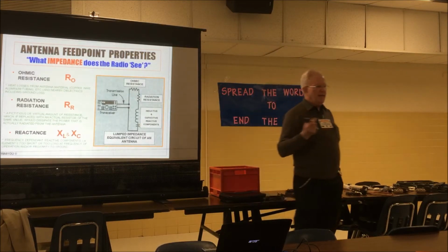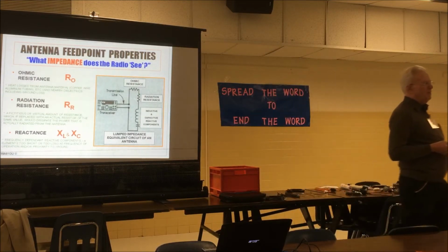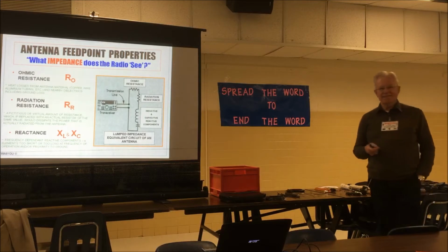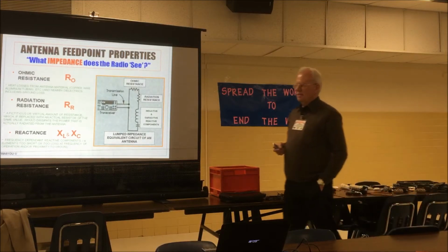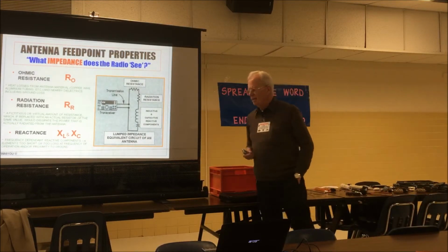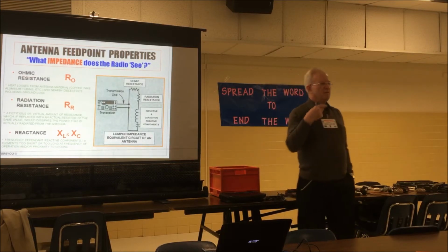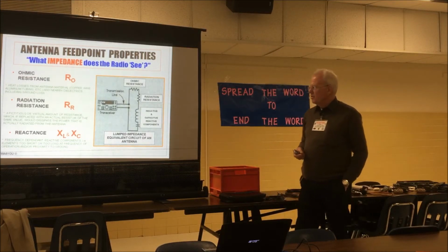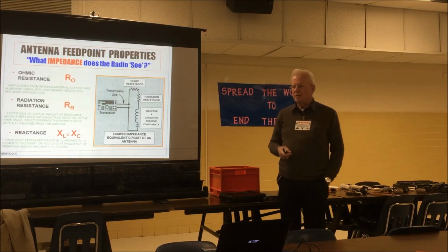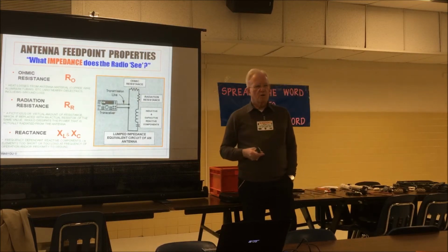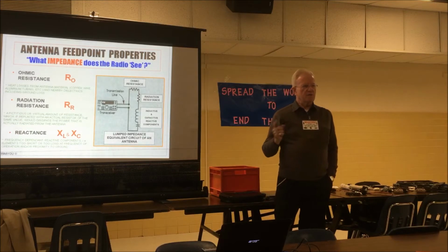And now the two bad nasty things. These are the nasties, you know, reactance. I think it's kind of strange that if you got an antenna that's too long for the frequency that you want to use, then it looks like a coil and a resistor in series.